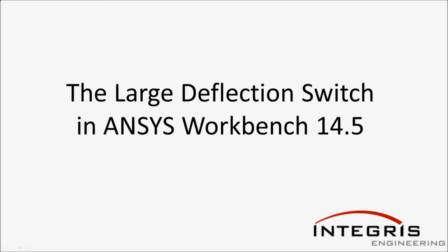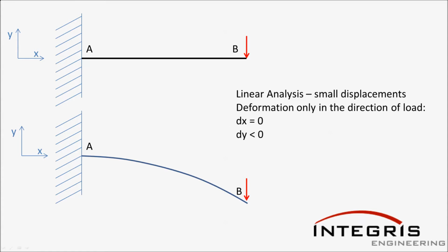In this video, we'll look at the large deflection switch in ANSYS Workbench 14.5. In linear analysis, one of the major assumptions is small displacements. The resultant deformation is only then in the direction of the load.